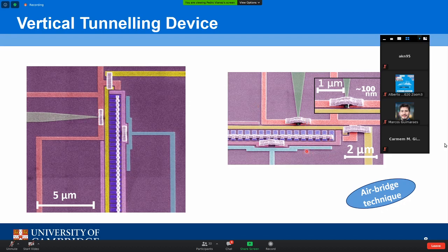And it also allows us to have more gates. So it allows us to introduce the P gate here. Like I said, the 1D region is in here, but in order to inject current into the wires, you have this 2D region. And by having a gate there, you can move this region around and map it separately, and you can subtract it from the data. So we can only look at our 1D-2D signal instead of having this parasitic signal on. And that was an improvement we were able to make because of this gate here.